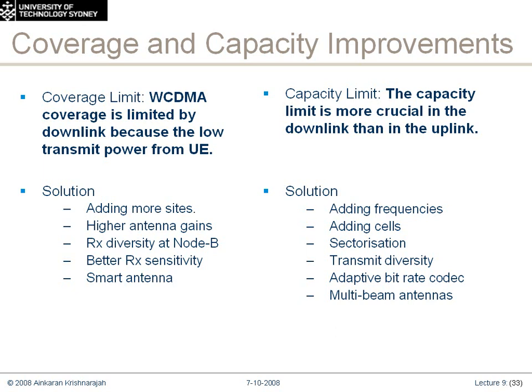The question was, does it change automatically or manually? It changes automatically. So based on the measurements that are being taken from the network, the base station is then able to power and control the antenna to actually, to some degree, it's not specifically like tracking a single user, but the lobes change to deliver the power to certain parts of the sector. So 1 or 2 degrees, like that. Yeah, something like that. So you can think of in a 3-sector base station, that sector then is broken down into subsectors. And then you deliver power to maybe 1 or 2 of them more so than the third or the fourth one.